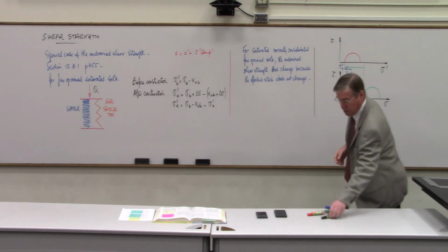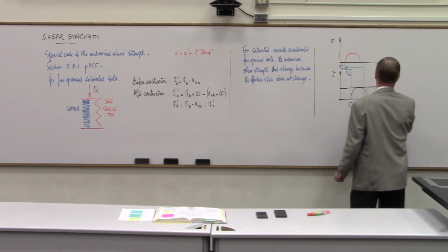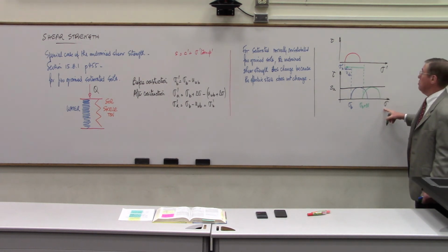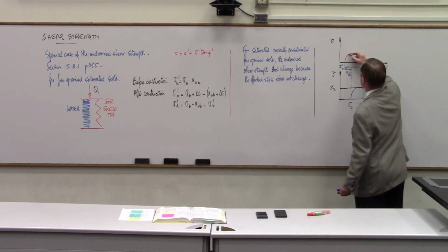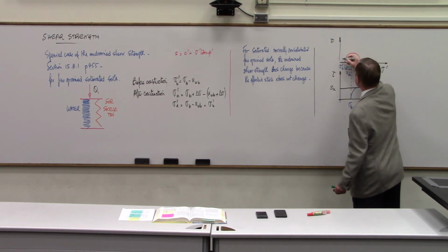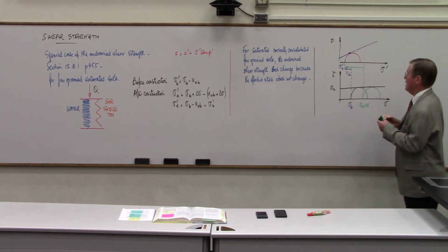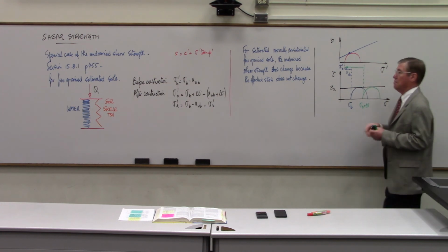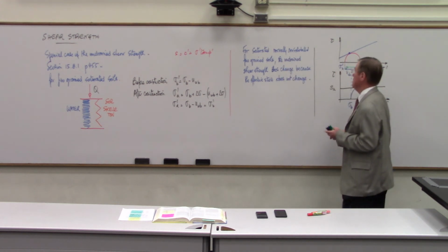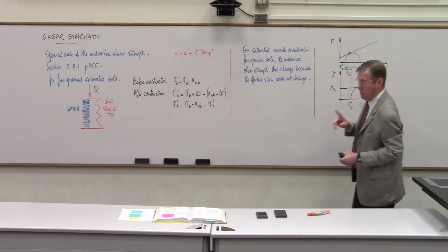And it looks like this undrained shear strength is a constant in the total stress set of axes, when in fact the effective stress is guided by the same expression, which is right here. So you can actually express the undrained shear strength by this equation, which always works. Okay? But this is a special case, and it turns out to be pretty useful. And I'll finish with one example.